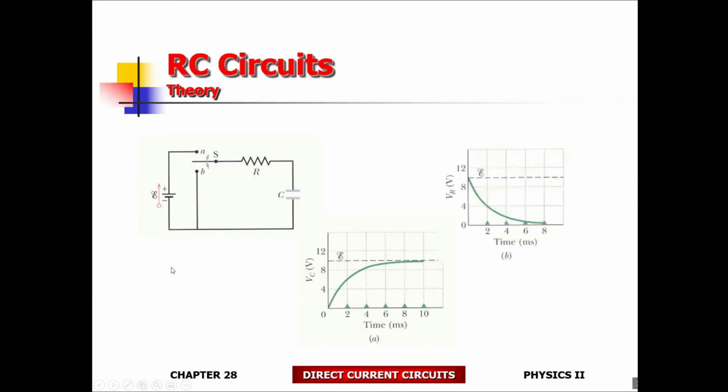How fast you're going to charge it up depends on your capacitance value and on your resistance. And then you turn the switch off, and now it's going to discharge. Notice that the discharge is an exponential process. There's an exponential decay. So mathematically, this one is straightforward, and this one is slightly more complicated. This is not an exponential increase, but an exponential decay.